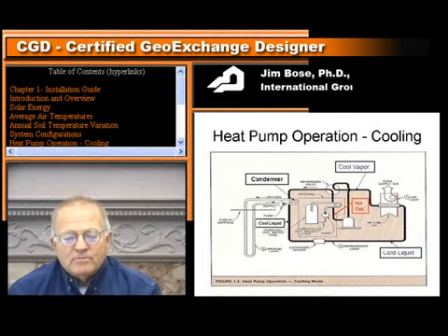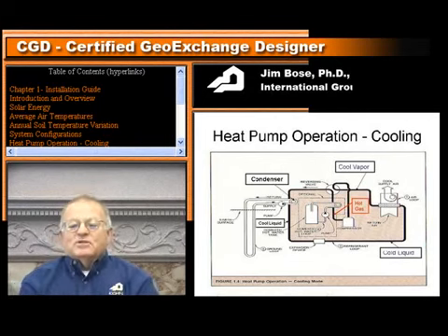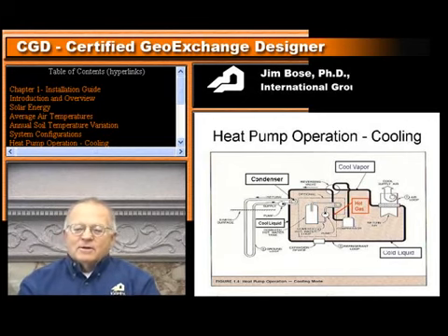That warm liquid then comes to the expansion device. The expansion device drops the pressure, and as it exits the expansion device in the refrigerant loop, it comes out as a cold liquid. That cold liquid then continues its journey up into the air loop. Okay, so that's the evaporator coil now. So that cold liquid comes into the evaporator. The warm air of the building load then comes across that, evaporates it. That's why I guess we call it an evaporator. It exits the evaporator as a cool vapor, comes down to the compressor, is then compressed again, and the cycle continues.